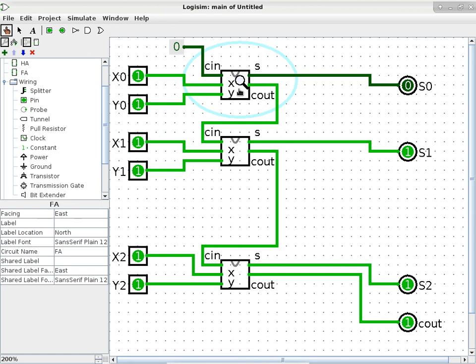So this is called carry rippling, because it's kind of like a ripple effect. You cast a stone into a lake, okay, the ripple goes in here, and then that ripple in return generates another ripple, and so on. Now this picture doesn't really quite convey the problem because we are only dealing with 3 bits. But when you imagine this is like 64 bits long, then you will start to see, wow, that's really a lot of waiting for the answer of the previous full adder.